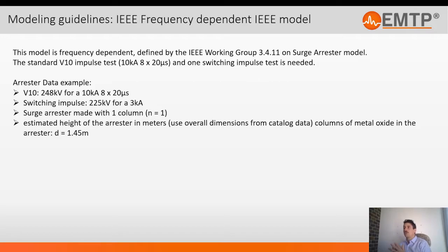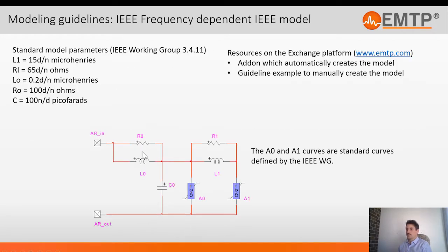Basically this model is an aggregation of several models. It actually looks like this. It's an aggregation of several devices. So you will have two nonlinear resistances, which are exponentially fitted, and an arrangement of RLC circuits. So this is the surge arrestor. It's kind of a small circuit, but this is the model 1 surge arrestor. And in this procedure, we will basically adjust all the RLC components as well as those two curves to fit the switching and the lightning curves.